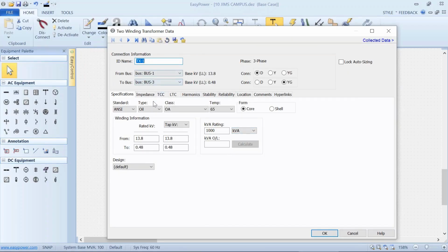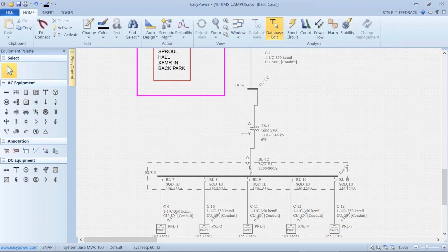two-winding transformer dialog box, when we set up the information for this transformer, we normally tap it at the same ratio that we have for the voltage. And so this is assuming a perfect transfer of current across the turns. If we put 13.8 in, we get 0.48 out, kilovolts.